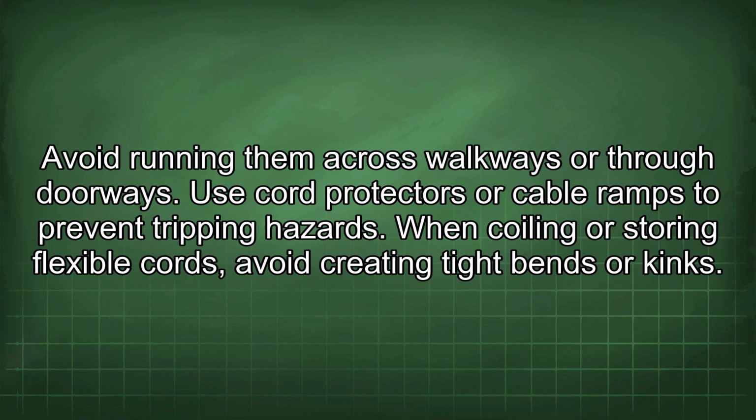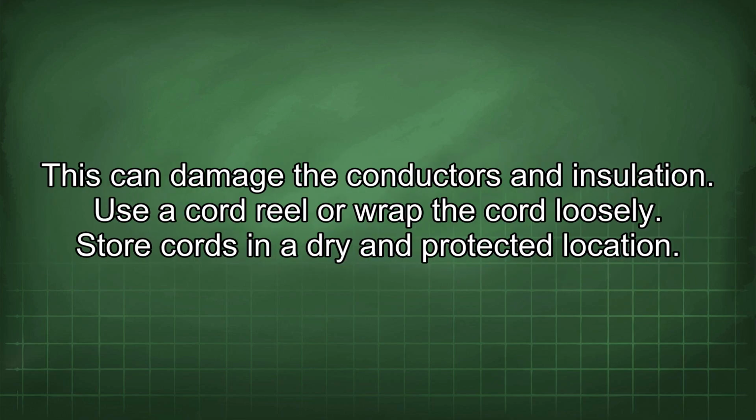When coiling or storing flexible cords, avoid creating tight bends or kinks. This can damage the conductors and insulation. Use a cord reel or wrap the cord loosely. Store cords in a dry and protected location.